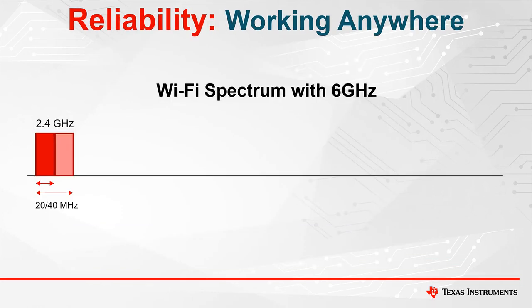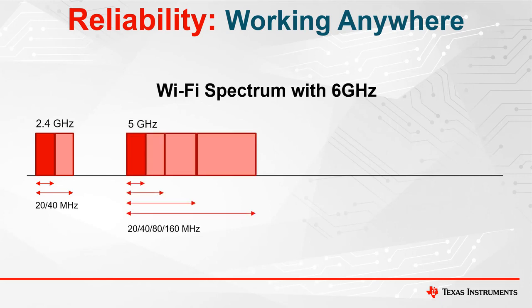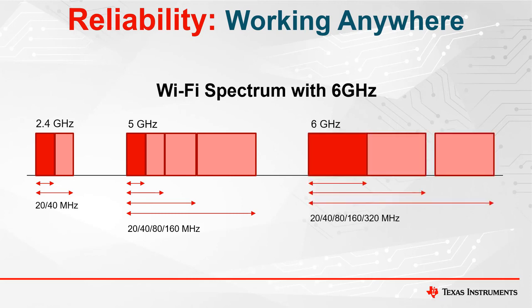The original Wi-Fi 2.4 GHz band used to be a bottleneck. The limited number of Wi-Fi 20 MHz channels, together with other wireless technologies operating in the same range, made it very congested, with an impact on overall performance. The 802.11a spec added more sparse channels in the 5 GHz band. The latest standard, Wi-Fi 6E, adds a third band in the relatively unexploited 6 GHz, with up to 100 new 20 MHz channels compared to the original 11 channels in the 2.4 GHz.